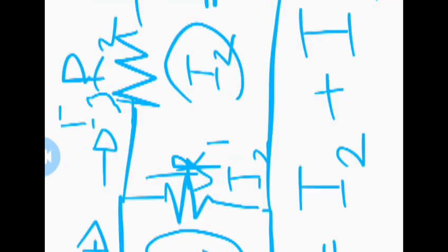We can reconfigure the foundational Kirchhoff's current law to figure out that I3 equals I1 minus I2, or 3 minus 1 equals 2 amperes, which means the current flowing in is 3 amperes, the current flowing through these two circuits is 1 ampere, and the current flowing through here is 2 amperes. That's as simple as it goes.